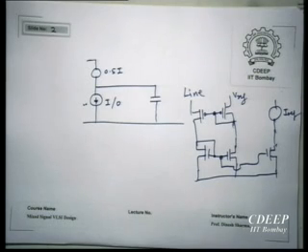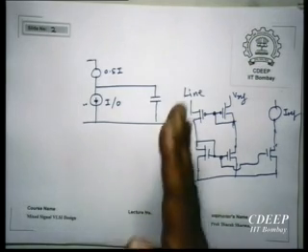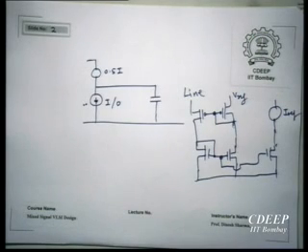Suppose I make this ratio 20, I will have double the amount of current. And the rest of the design before this point will not change at all. All that will change is this ratio, this current multiplier ratio. So I can choose anything that I want and make a compromise between speed and power. Got this? On the other hand, however, it means that you can't have both. You are limited to this.